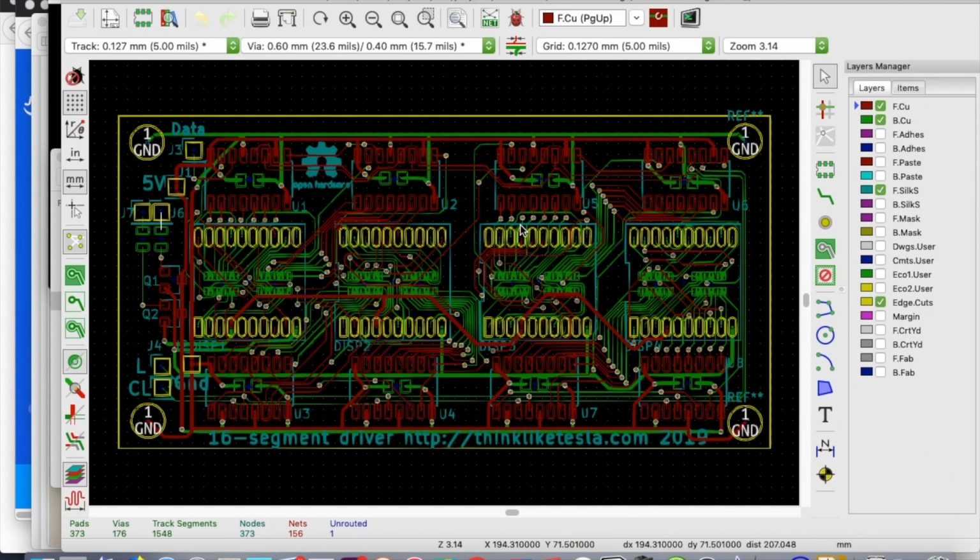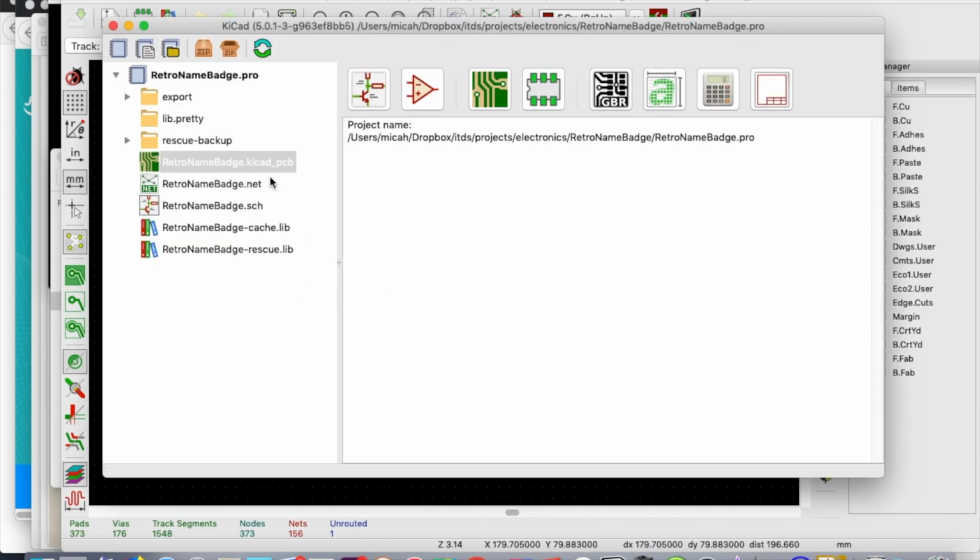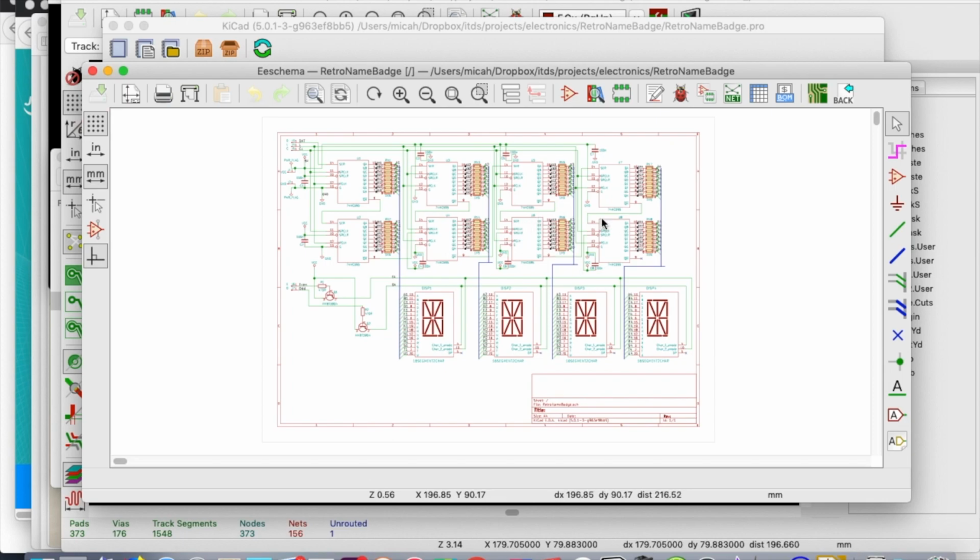And here we are, full circle again. Back to where we started this video from. This is the revised board here. Notice it's actually a lot simpler because in redoing the board, I discovered an error I had made. I had named all these nets, right? So I had 4 different 16-bit buses on the schematic. Remember the schematic here? It's got 1, 2, 3, 4 different 16-bit buses.